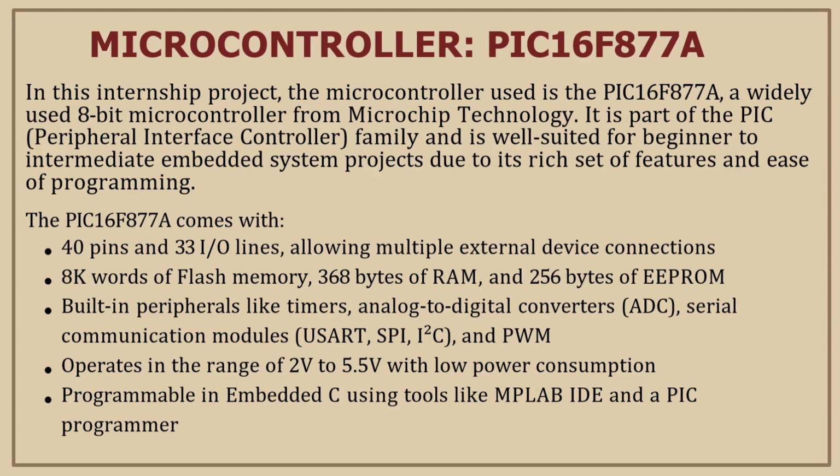The PIC16F877A comes with 40 pins and 33 input-output lines, allowing multiple external device connections, 8K words of flash memory, 368 bytes of RAM, and 256 bytes of EEPROM. It has built-in peripherals like timers, analog to digital converters, serial communication modules, and PWM. It operates in the range of 2 volt to 5.5 volt with low power consumption, and is programmable in embedded C using tools like MPLAB IDE and a PIC programmer.